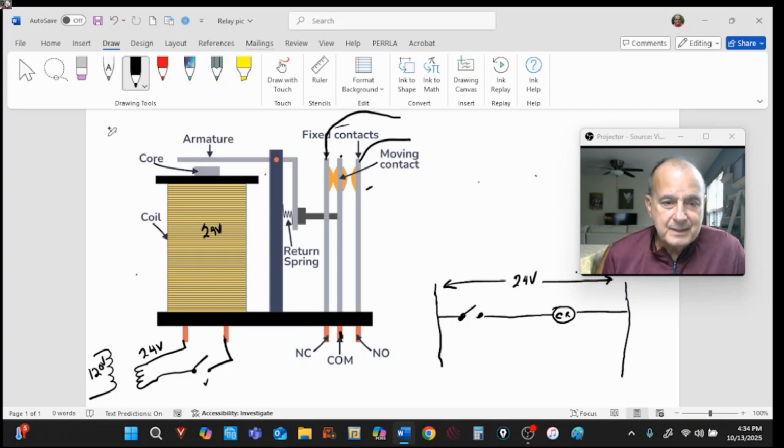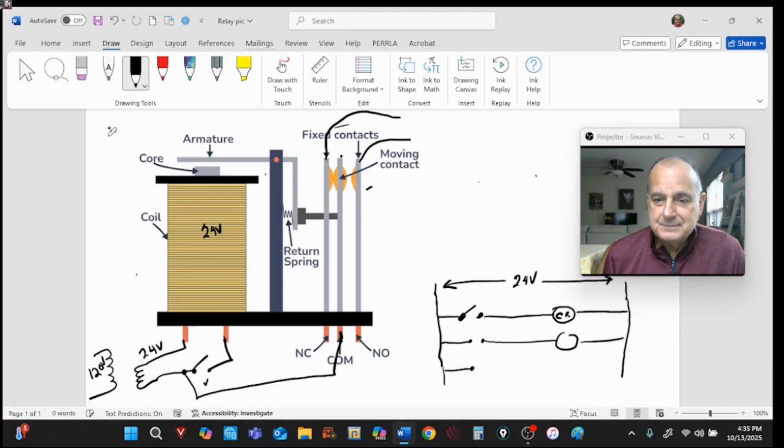We're going to steal from the primary side of our switch. We're going to go feed our common. If we were going to wire that here, we'd come off this power, unswitched, and then go to some kind of contact that's here, and then go to a light. And we'll come off another contact here, because we have the two contacts, one normally open, one normally closed, and we'll go to another light here.